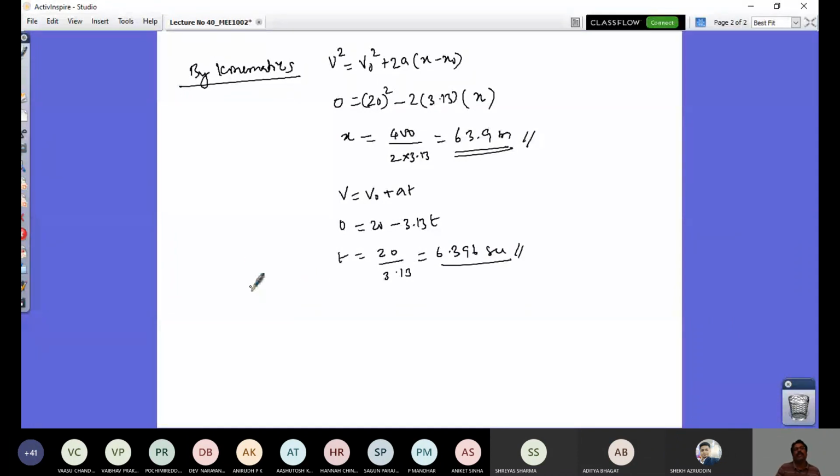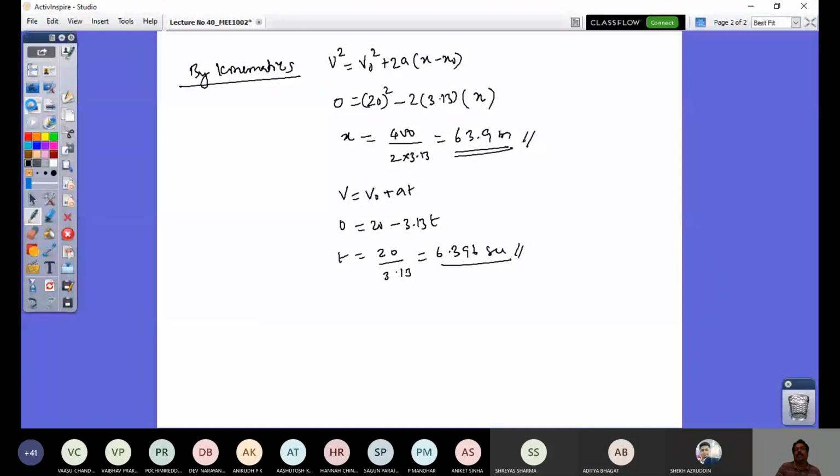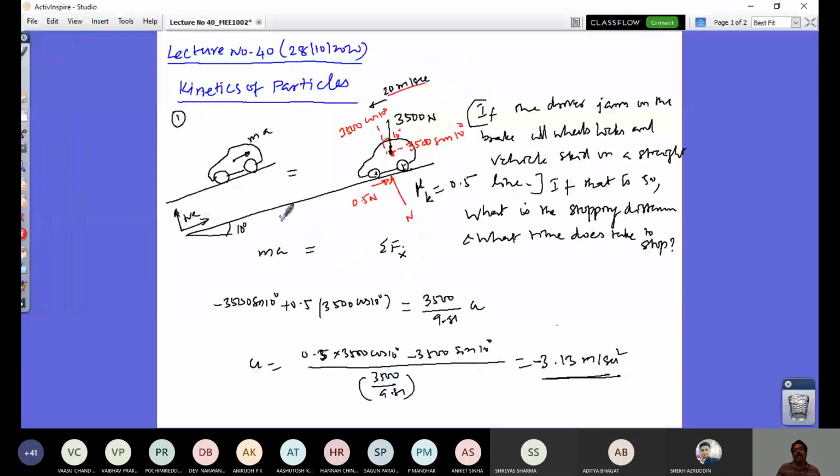So we did kinematics first in hand because you'll have to solve problems where you are not knowing any of the motion parameters. You are given data like that. You require at least one motion parameter, and the readily available motion parameter from the fundamental governing equation of motion is acceleration, and that we get by applying Newton's second law. So here when I apply that, I get my deceleration rate, and I use that in my kinematic equation, which I have already studied for a rectilinear motion.